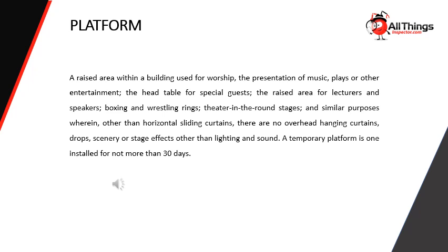Platform. A raised area within a building used for worship, the presentation of music, plays, or other entertainment, the head table for special guests, the raised area for lectures and speakers, boxing and wrestling rings, theater in the round stages, and similar purposes wherein, other than horizontal sliding curtains, there are no overhead hanging curtains, drops, scenery, or stage effects other than the lighting and sound. A temporary platform is one installed for not more than 30 days.